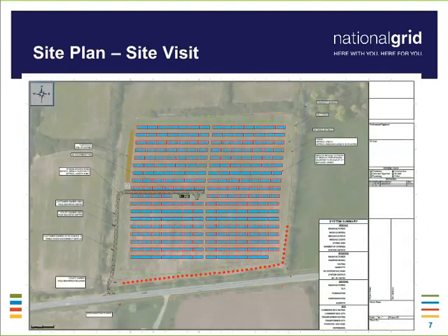Moving on, when we get to the initial site visit, like I said, through the CESIR, we'll ask for a revised site plan, and it will look something like this. Something a little bit more detailed, a little bit better picture of the array. You'll see an access road along here, customer's proposed pole line, some notes on the pole line, what each pole is, utility-owned pole, customer-owned pole, what is disconnect switch, utility pole for the meter, and so forth. We'll also see property lines and fence lines. And this is good enough for us to get out in the field and take a look.